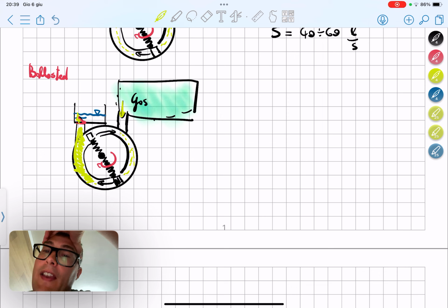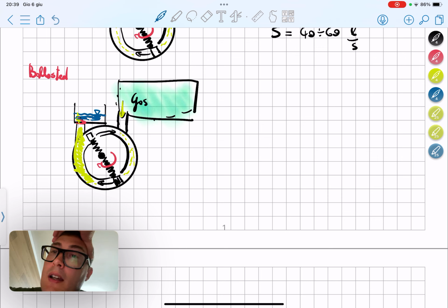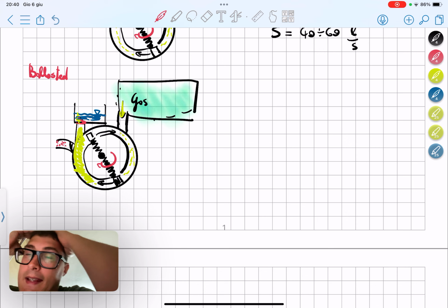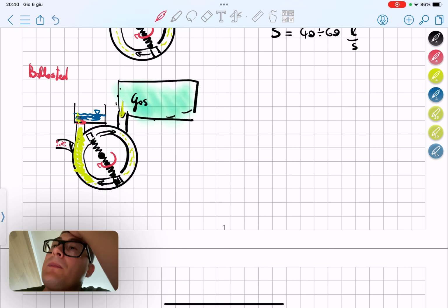So there is a phase transition from a gas into a liquid form, and therefore it can spoil the oil, this blue oil here, and we need to change it often. So the way to solve this is to create little valves here with some so-called ballast gases that essentially reduce or completely mitigate this liquefaction.